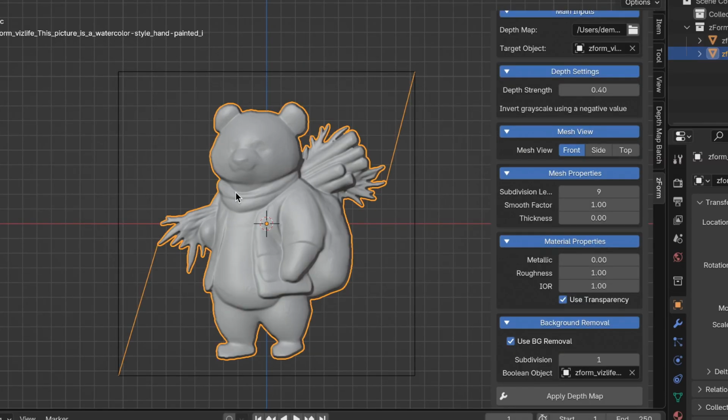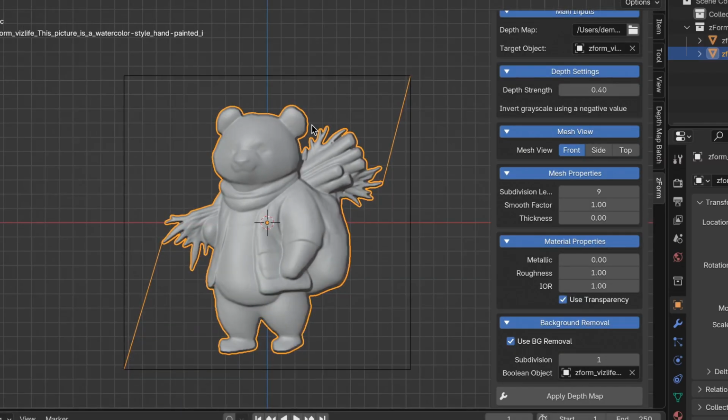Okay, we're getting somewhere. Now you'll see one issue. There are 2 outlier vertices in the mesh, one on the top right and one on the bottom left. We have 2 options. We can either remove those 2 vertices after we apply all modifiers, or we can adjust the cube a little bit more to see if it will remove those vertices, as well as seal the backside. Let's try the latter first.